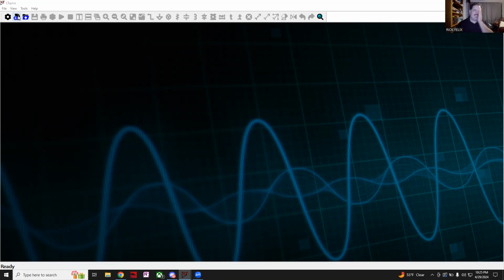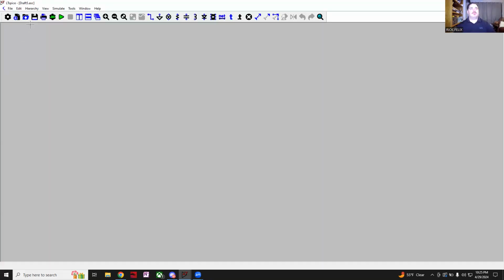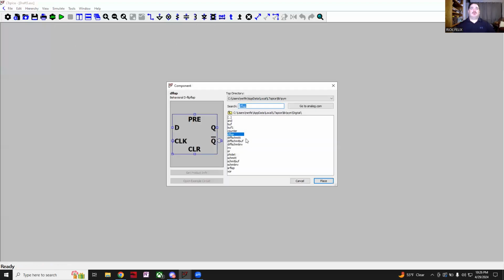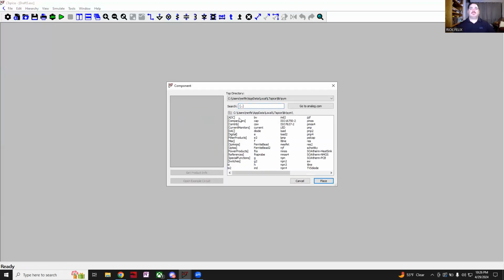This is an LTSpice demonstration video to create a shift register using flip-flops and pulse input voltage sources. To start this process off, you're going to want to create a new drawing by clicking on the new schematic. Next, we're going to plop down 4 D flip-flops.